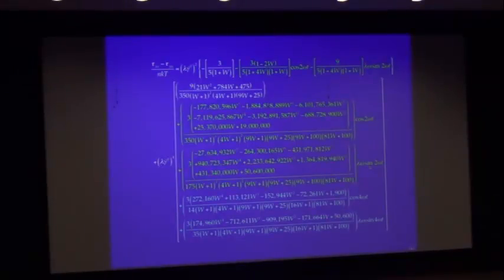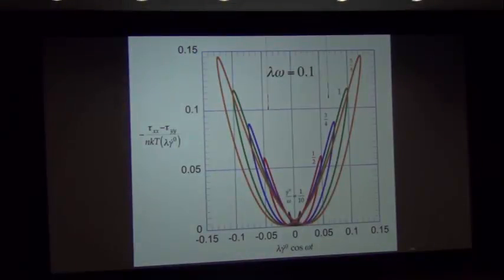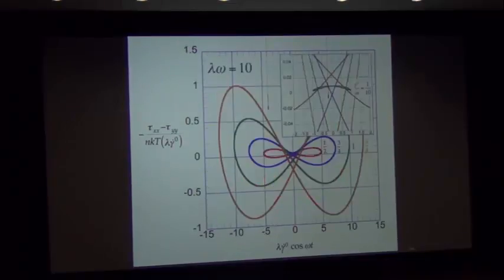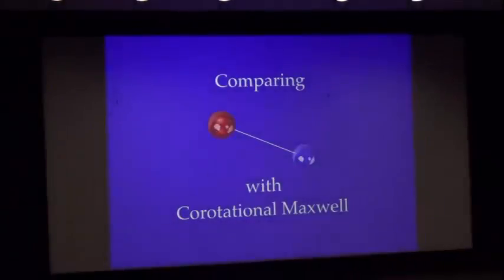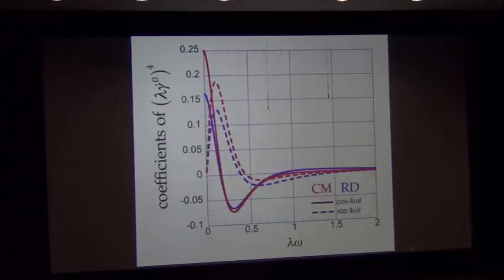Because you're trying to damp a vibration like this. I didn't mention this before, but you're not only getting in-plane forces at 3 and 5, but you're getting normal forces at 2 omega, 4 omega, and of course a steady value also. And so they find these equations useful for redesigning viscous damper fluids. And of course, we've got our old friends, the bow ties, coming out from the molecular theory. And now we can do the comparisons that we talked about. Hey, I don't want to focus too much on this, except to say we found the same remarkable qualitative agreement for the first normal stress difference.